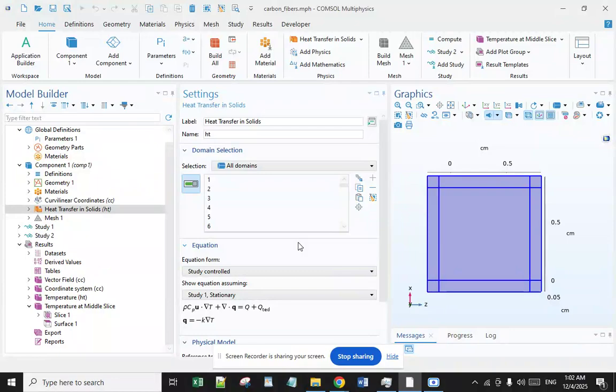Correlations of heat transfer were investigated on the basis of internal flow rather than external flow, and it was found that the non-uniformity of the fiber location and cohesion of fibers strongly affect the heat transfer characteristics. And thermal conductivity modeling and characterization for woven fabric polymer composites modified with nanofillers. Woven fabric polymer, or WFP, composites inherently possess a low thermal conductivity, which limits their applications in thermal management.